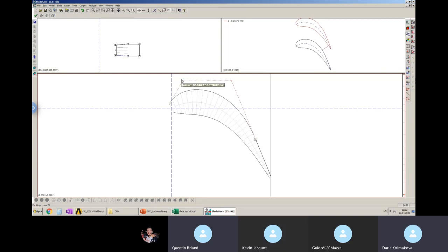I don't know, maybe you have a different picture because you've changed the position of different points, but in my case I need to change the position of this throat closer to the trailing edge. Because for a rotor blade, what's the best position for the throat? Exactly the same as for the normal vane, near the trailing edge of the blades. Something like this.